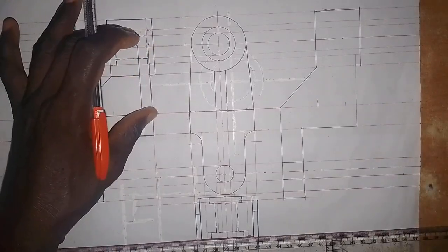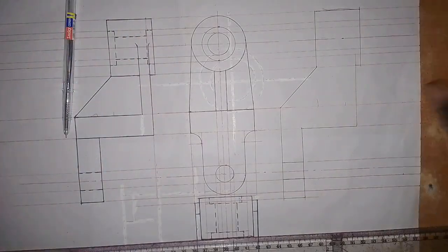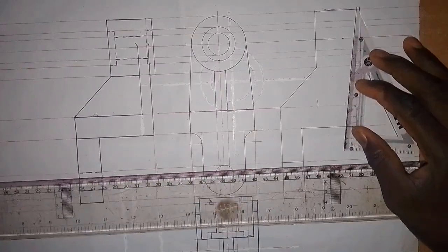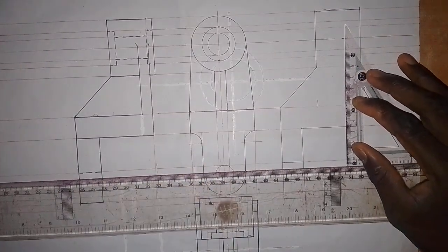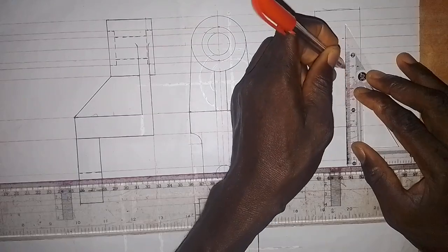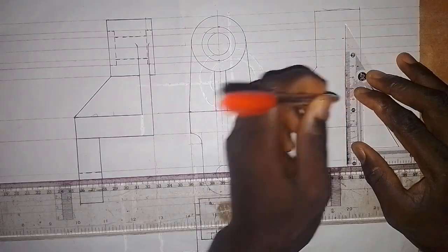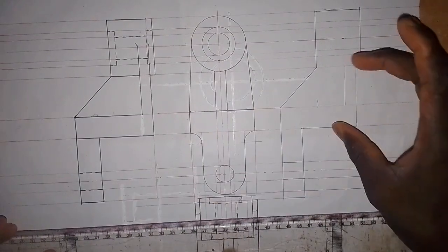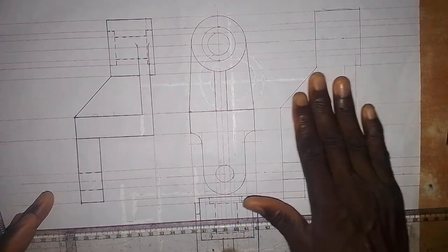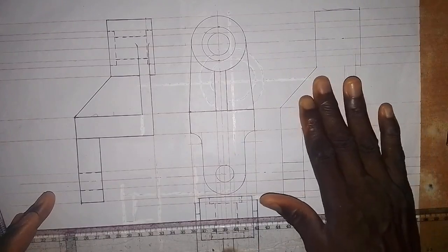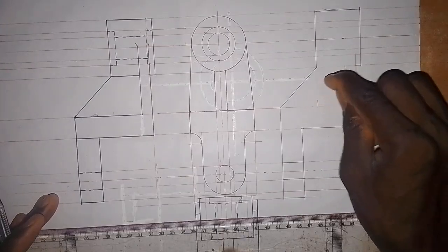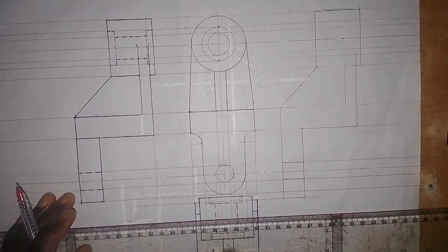Unlike as we see it here, it will not be like this in the sectional view. So we draw a line, and it will still be drawn with a thin line. We just draw a line from here to touch this line here like this. So this is how we are to have it. Though we are not going to make it a thick line, because by the time we cut it off, it will be merged with this one, in which both of them are supposed to be plain, but we are still going to hash this one. It's only this one that is meant for the web that we are not going to hash. You see how I'm going to work it out.